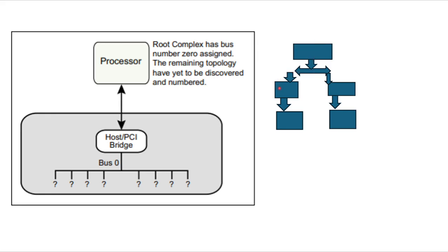Whenever you want to drive any memory traffic, you have to enable the memory space enable bit in the devices. Then this component will respond to the memory request. Otherwise, it will send an unsupported request. You have to configure the devices before sending actual packets.